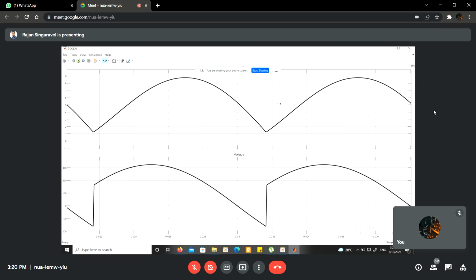It means that finally the power is delivered from the source side to the load side to the source side. This will be the scenario, right? So this condition of operation is called inverter mode operation. Inverter mode operation in the sense it is not a DC to AC inverter, but the power is inverted. Power is transferred from load to source.